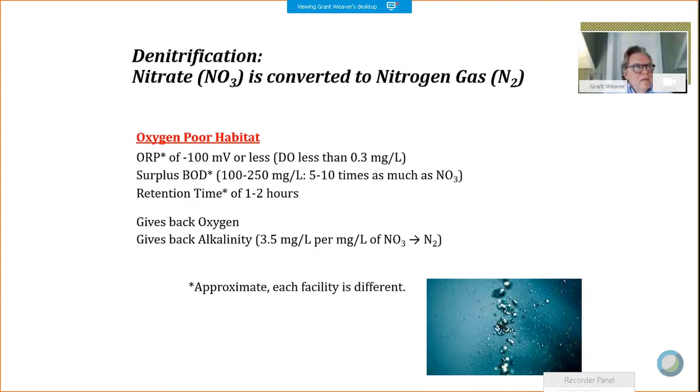Again, some rule of thumb targets to get the process started. A lot of BOD, so look at that. For nutrient removal, we're going to see that as an ongoing thing. Nutrient removal requires a lot of soluble organic matter, a lot of BOD that would be consumed in the first hours in a BOD bottle. The more the better, actually, for nutrient removal.